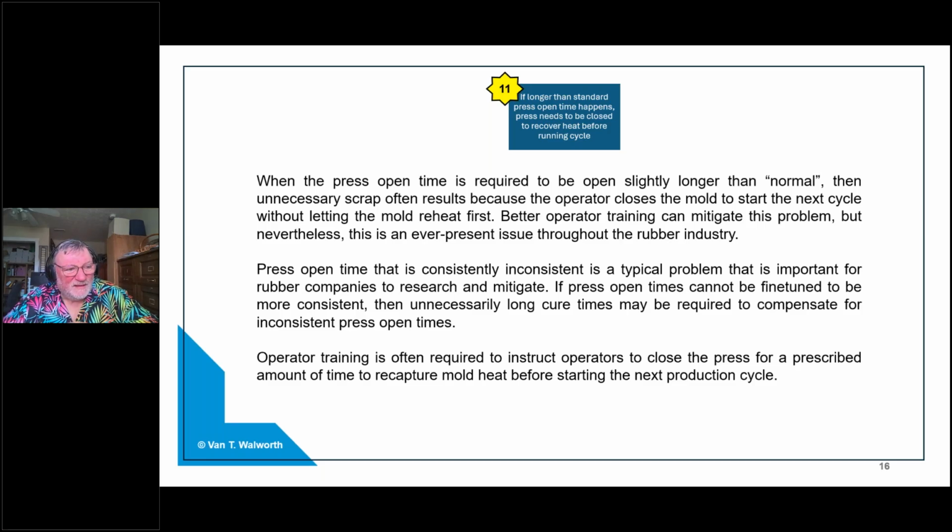It's usually with new operators that haven't been trained to close the press up and let it regain heat before starting the next cycle if it was open for some period of time that it shouldn't have been, or it's someone that doesn't care. They're just running it. They're just marking time on the job.